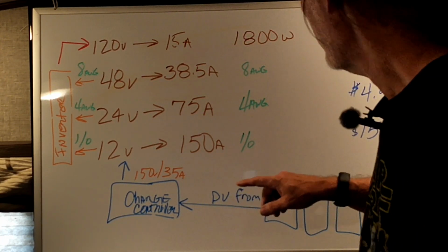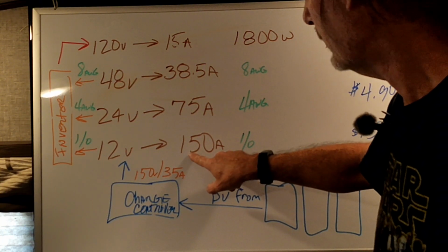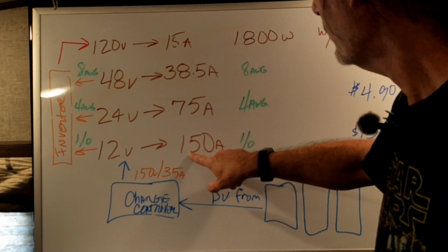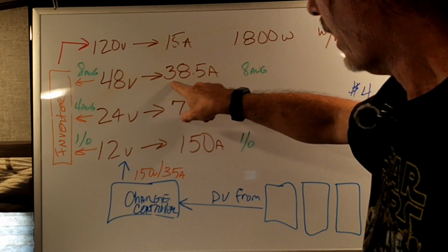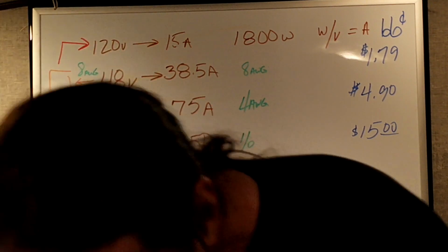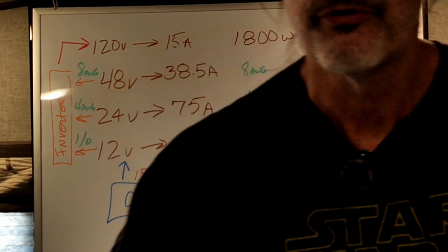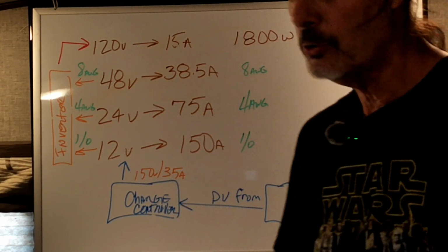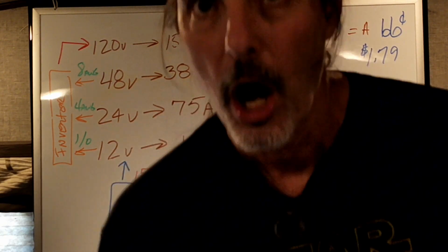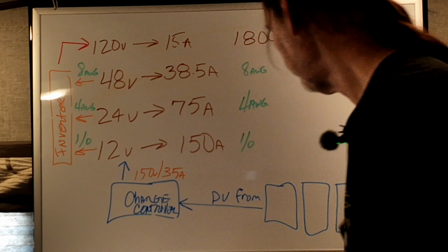So, 35 amps, obviously here, 15 amps is 1800 watts, and 15 amps here is a whole lot more. So, let's do the math on what this means the maximum charge rate for each one of these batteries could be. And let's just assume that you have 400-watt panels that we've listed down here.